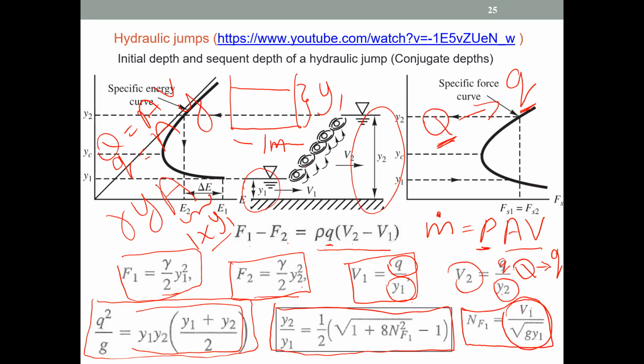What you need to find out is how the depth changed. That is in terms of the entrance depth, Y1, your supercritical flow depth. Then you have the Froude number, and you can calculate Y2. A very simple equation. Y2 is in terms of Y1 and the Froude number. Substitute them, and you can find Y2, right?